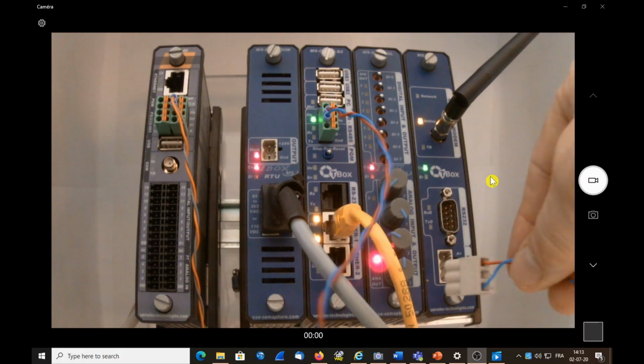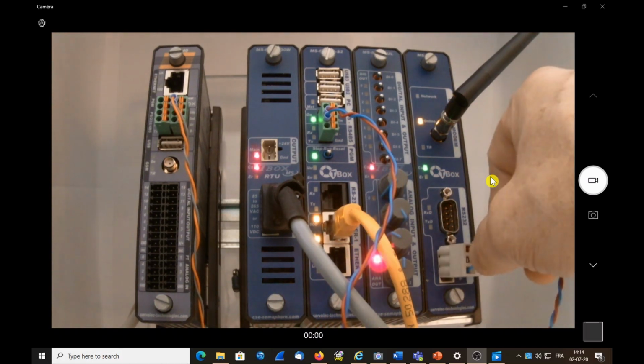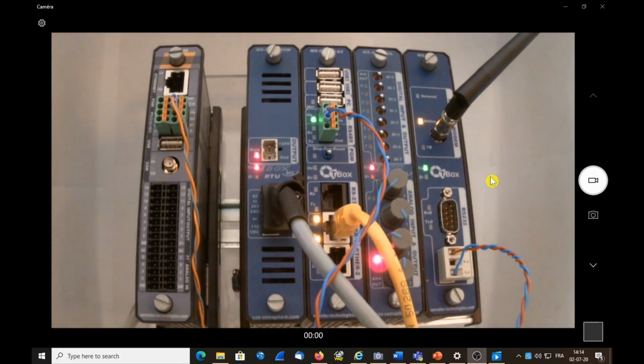I will cable it to the RS-485 of the GSM card, and both ports will communicate together, because in T-Box each port is independent from each other, and each port can be master and can be slave. So we will declare the resources of the electrical meter into T-Box.